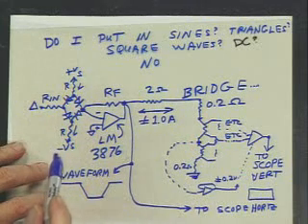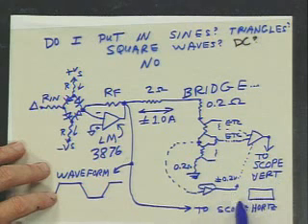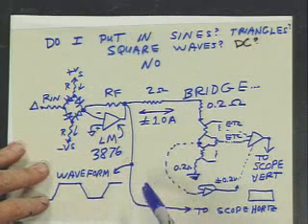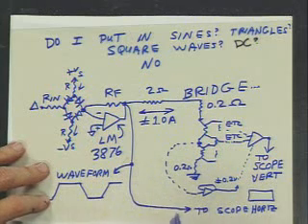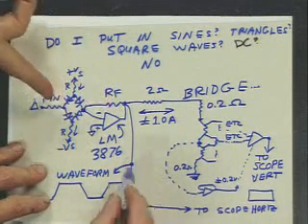And then you can cross-plot it on a scope. Yeah, and I cross-plot this in the scope. The scope gives a cross and up and cross and down and cross and up and cross and down. This is a trapezoidal waveform, and a trapezoidal waveform gives best results. And that's not a trapezoid because of slew rate limit on this amp. No, it's because of this.